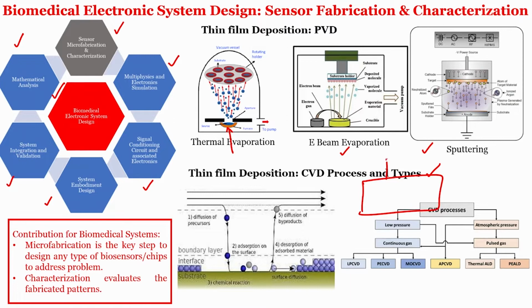If this is the step that you want to cover, and you deposit the material using PVD, what happens is it will get deposited, but this area will not be covered correctly, right. But if you go for CVD, then because the gas is everywhere, it will react uniformly and the step will be covered. So, that is the advantage of CVD over PVD.